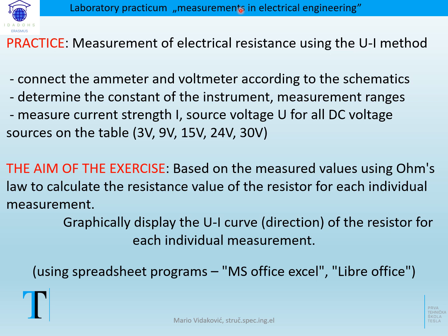First schematic, the ampermeter in front of the voltmeter, and second schematic, the voltmeter in front of the ampermeter, because we need to measure two times. For the first schematic, we need to measure for the resistance which is small and for a bigger one, and we must connect the other schematic, the voltmeter in front of the ampermeter, for the smaller resistance and for the bigger resistance. And we must compare the results to see which schematic is better for which consumer.